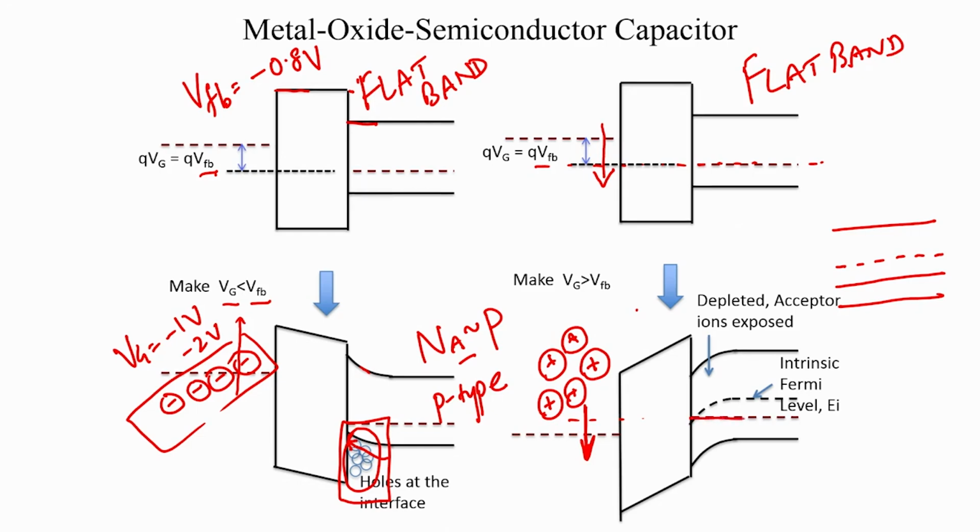So, this is the Fermi level after doping and this is the aligned Fermi level, and we have also indicated the intrinsic Fermi level here, and that is a very good indicator, because if you recollect, your electron concentration is dependent on the exponential of EF minus EI by kT.